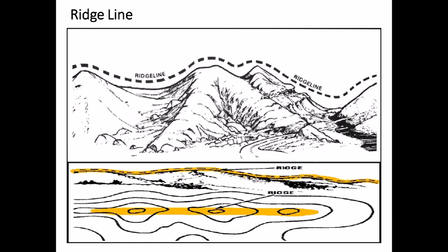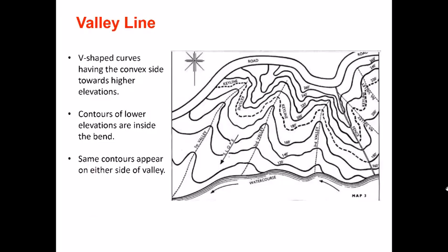This is represented on a contour map by these three series of concentric circles. That means in the centers we have three hills. Otherwise, we have land which is at the same gradient, joining all these three hills. So if you have a contour map that's something like this, this shows you that this is a ridge, and this ridge line on a contour map is shown by a series of concentric circles in a straight line. So that is basically a ridge line.